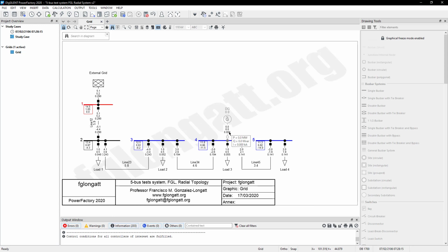Opening the circuit breaker in PowerFactory is different to an outage or putting out the service. When you say out of service, that means that the component, the device, is removed from the calculations. But when you open a circuit breaker inside PowerFactory, PowerFactory keeps this device, and this device is included in the calculations. And you can see over there, it's saying 0. All the results are 0 for this machine. However, it's taken into account for the numerical solution, okay? Probably for load flow it is nothing really important for you, but in other videos of mine regarding power system dynamics, you will see that this has a very important effect on your simulations, okay?